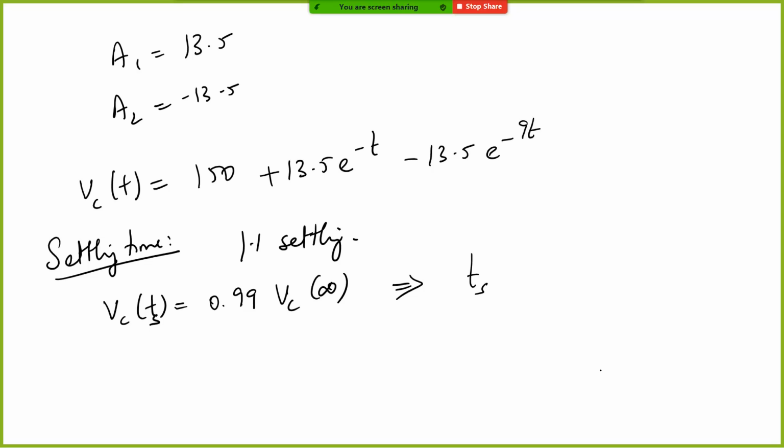So when you don't have a forced response, that settling time was in the context of the natural response only. There was no forcing function. That is, you energize the circuit and then remove all sources of energy, so the circuit is going to die down and eventually everything will go down to zero. In that context, when we talk about settling time, we talk about 1% of the maximum value. Let me explain. Thanks for bringing up this point; I didn't explain it.